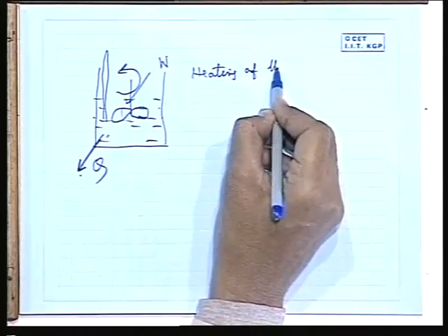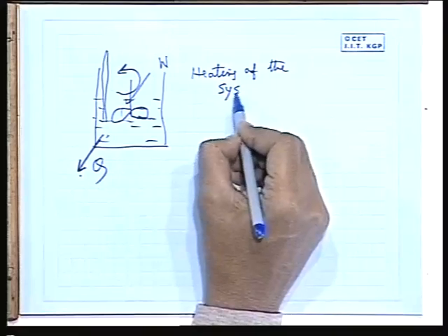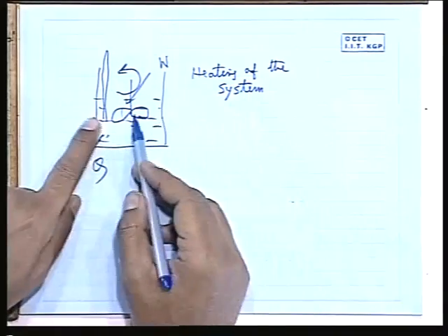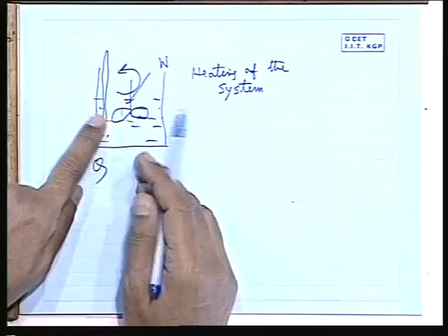Though the heat is taken out, it is heated because of this irreversibility. Some of the work is being dissipated through mechanical irreversibility into intermolecular energy, which raises the temperature. Whenever a system temperature is raised, we say it is heated.